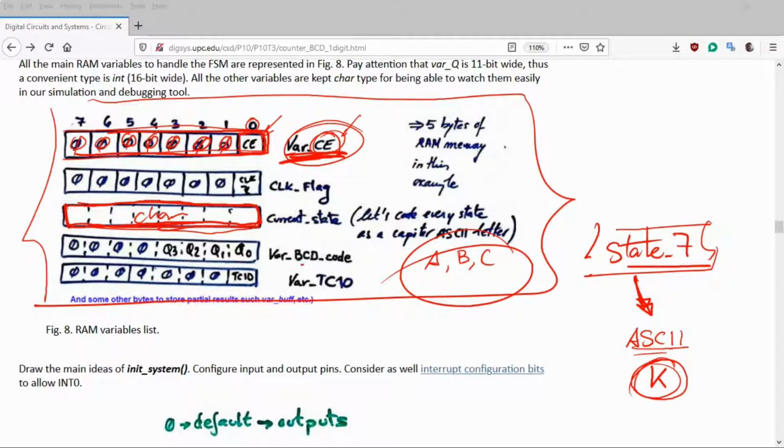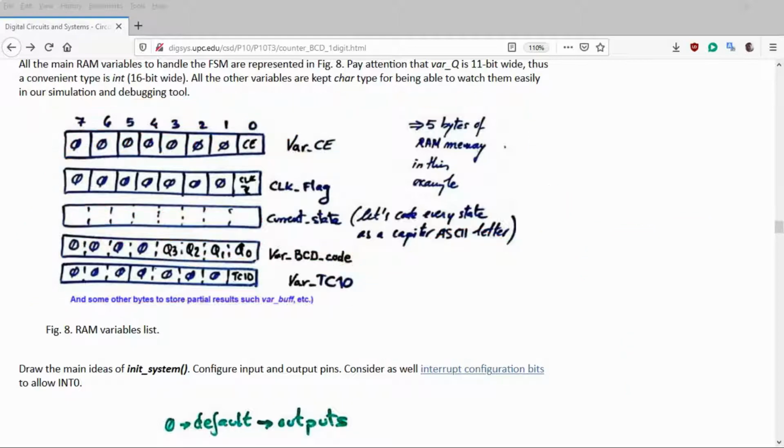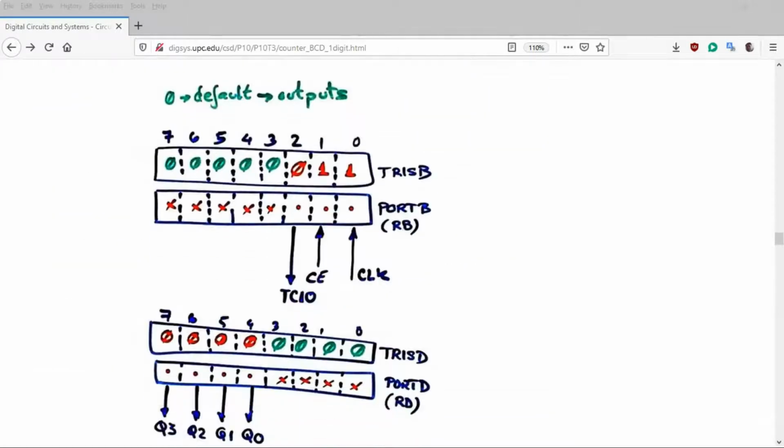If it happens that you have a BCD one-digit representation, a number from 0 up to 9, this is in binary 4-bit, and the 4-bit can be saved very well like this with another 4 leading zeros for keeping this variable in a single char, and that way all the time. Okay, so perhaps this explanation here is longer, but it's going to be the same and a lot faster for other examples.